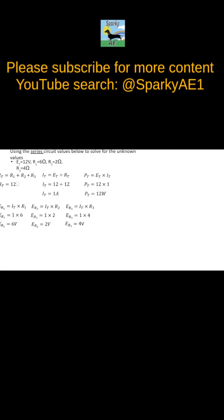Next, we find our current values at each resistor. For resistors 1, 2, and 3, we set the equations up, again using Ohm's law, as voltage drop at resistor 1 divided by resistor 1 value, and the same for resistor 2 and resistor 3. For the first resistor, we just divide 6 volts by 6 ohms.